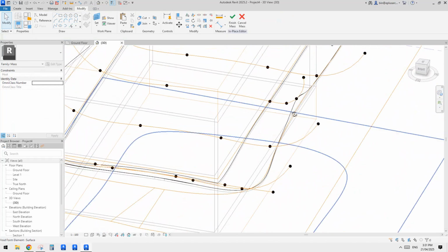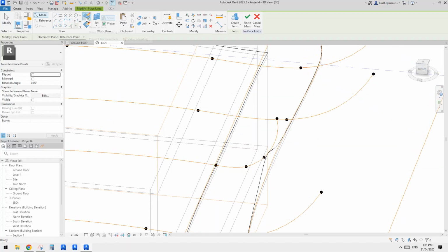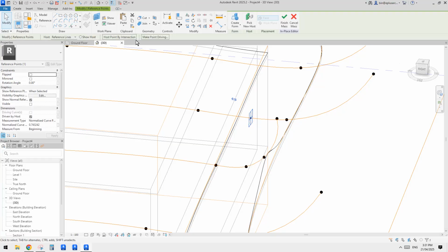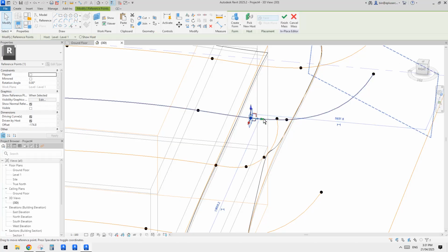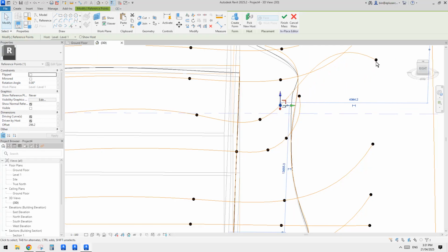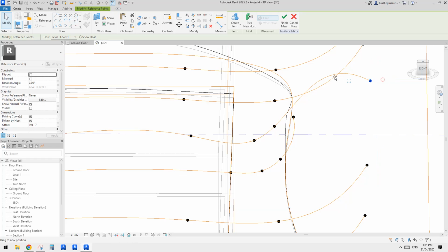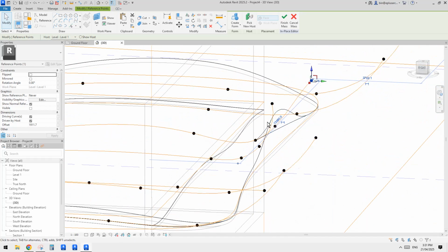And so let's do another one. So here, we add a point, draw on face, place onto reference line, escape, select it, make point driving, escape, select it again. So now we can control this point, right? We have a control point, and then we can just move this point, go up a little bit, go up a little bit more. Maybe this point needs to go to the left a little bit, right? So we create that curve.